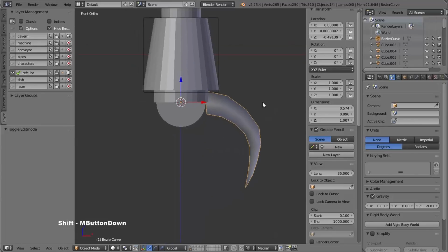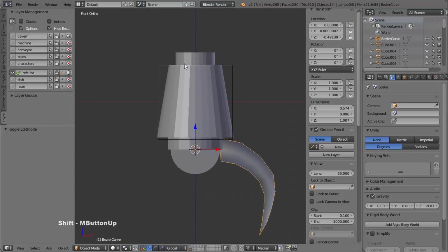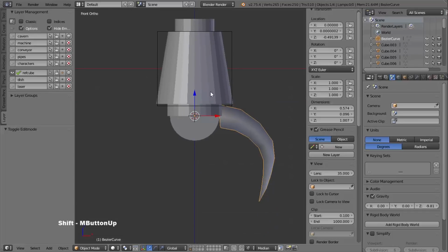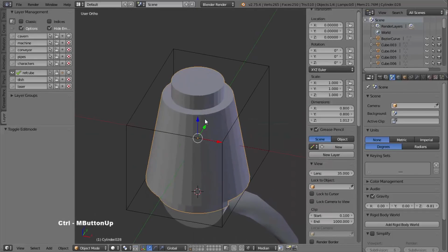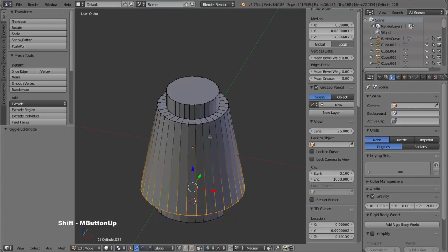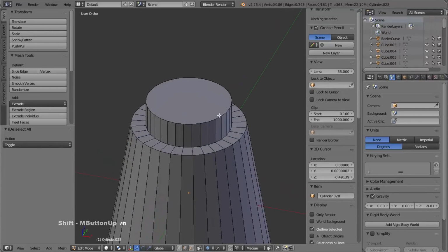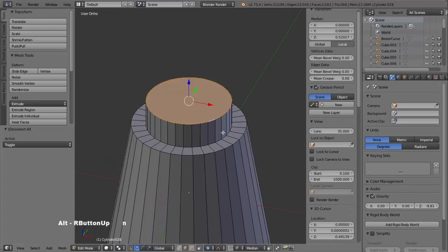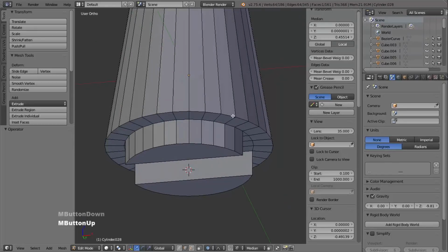Okay, so the next thing I want to do is start changing these objects and adding some smoothing and some bevels. So I'm going to go back to the main body and work on that first. So I'm going to hide everything else, and I want to go to edit mode and then edge mode and drop any current selections. And first of all I want to Alt and right click, and then Shift and Alt and right click on edges that I want to bevel.